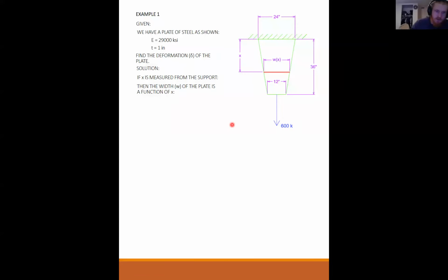The width is the only one that's a function. Okay, so the width is half of the area. Remember the three functions were area, Young's modulus, and the normal force. So yes, what you just said is absolutely right. The area is a function of the width, and the width is a function of X. So A is a variable, N and E are constant.